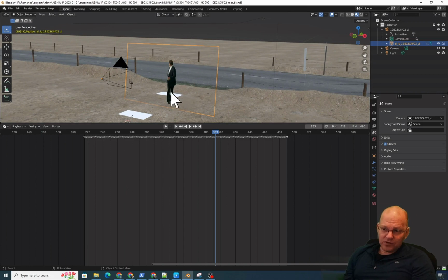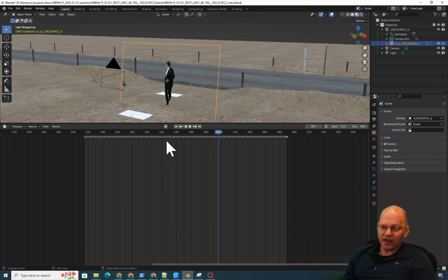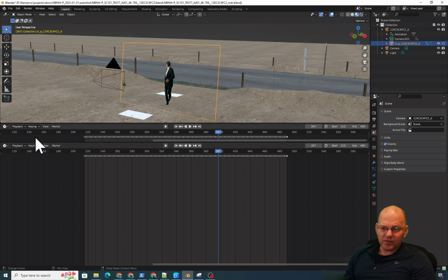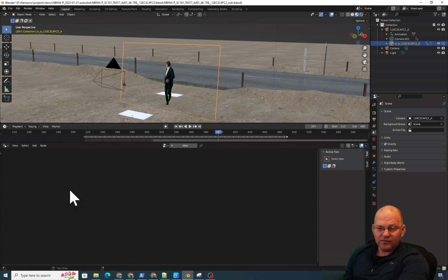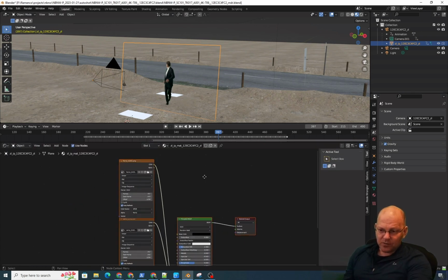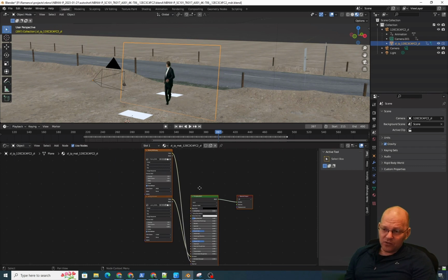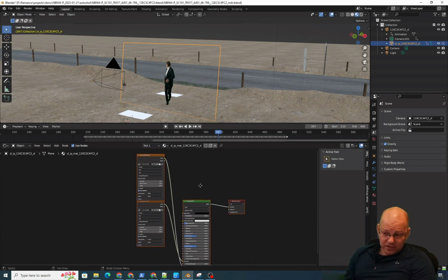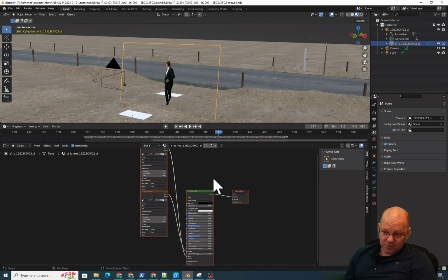And sometimes if you see your texture acting a little strange here, every other frame will be missing or something like that. So in case you run into that behavior, here's how to fix it. So we're going to right click here, we're going to do a horizontal split, move that a bit down. So we've got 2 timelines. Then we're going to go over here and Shift F3 until we have our material shading node group. So here you can see how the material group is built for the image plane. Note, this is not the compositing group. This is just the image plane.